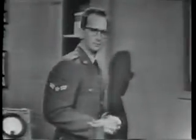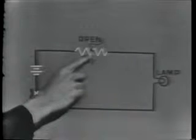The opens I've shown you so far could be found by visual inspection. That is, by simply looking the components over carefully. However, you will encounter opens that cannot be seen. In these, you'll have to use a meter that will detect the symptom that an open gives to this circuit. Here is a circuit to light a lamp. But because of the open resistor, the lamp will not light.